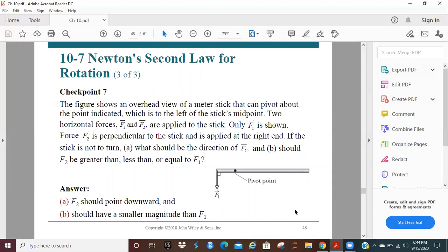So torque becomes a factor of not only R, but also of F. Since this length of R over here for this particular force is going to be much less than the R that's stretched over here, in order to produce the same torque, you're going to need less force out here to accomplish that.